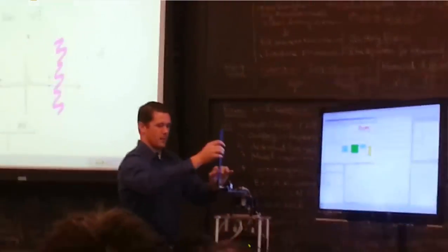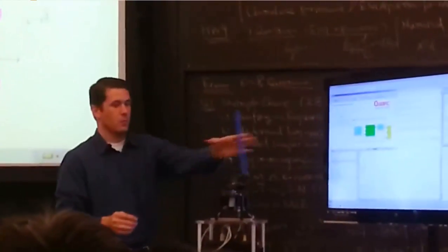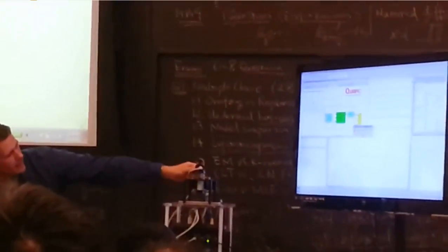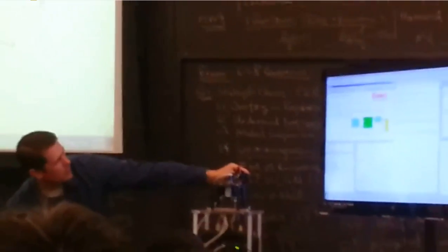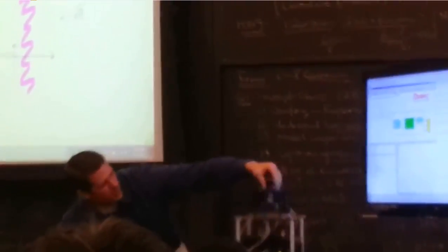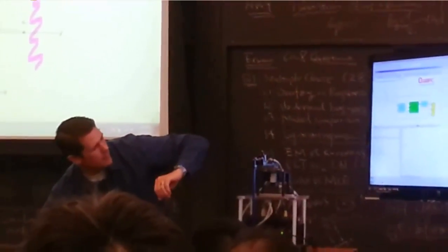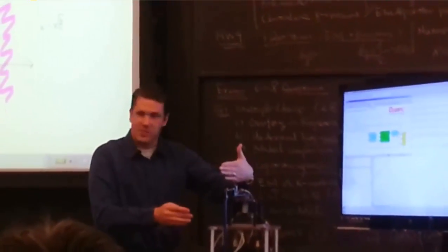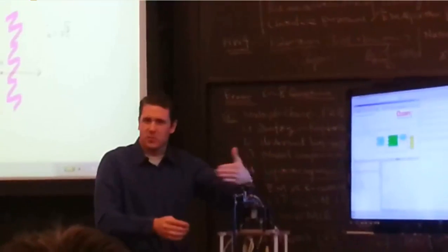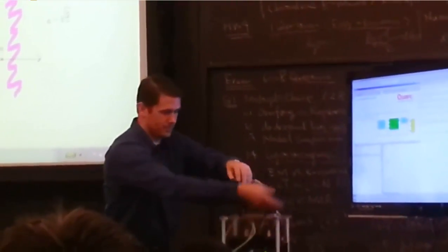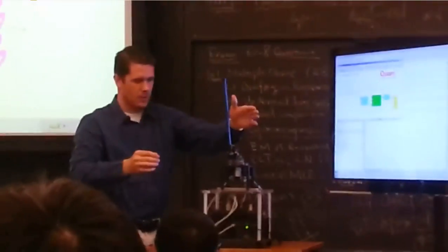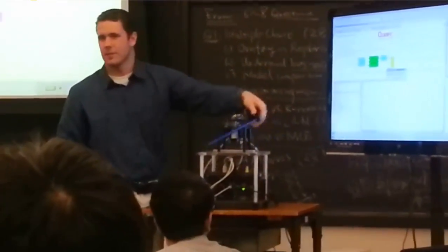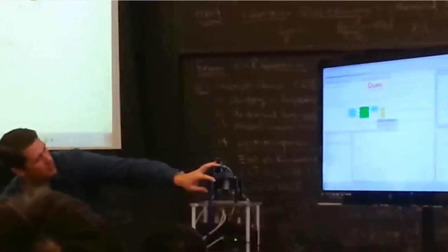Let's see once it gets up here. Okay. Ooh, see, it's sort of unstable. Let's do that again in case you didn't catch what was happening. So what's happening is it's not only trying to balance, but now it's trying to center itself here, and is doing it in sort of an unstable way, so it's going to keep oscillating back and forth. See, if I recenter it, then it's okay. But once it starts getting off, you see. So the proportional feedback, again, is not able to make it stable by itself.